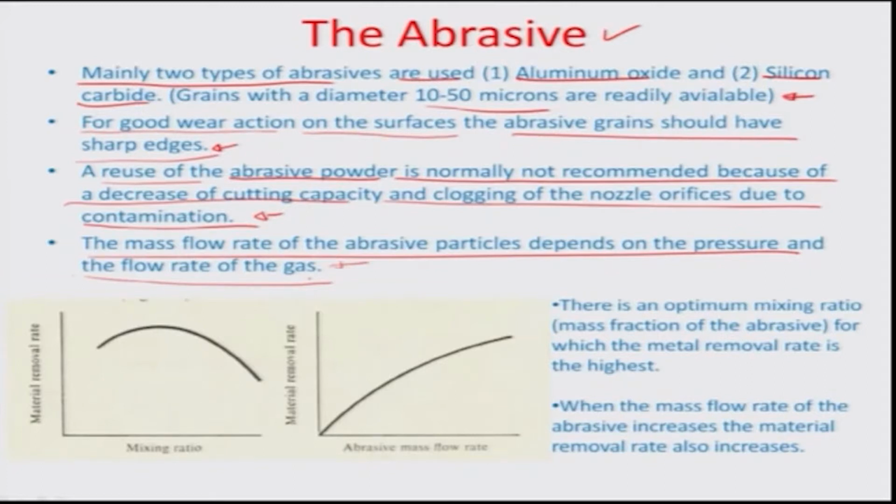Generally there is a tendency of metal flakes or the workpiece flakes to come with the flowing air and also the thrown up abrasive into the collecting pit corresponding to all these different abrasive grains. In fact, this is done in a large chamber where whatever is bounced off the surface in terms of abrasive grains falls on the base of the chamber.